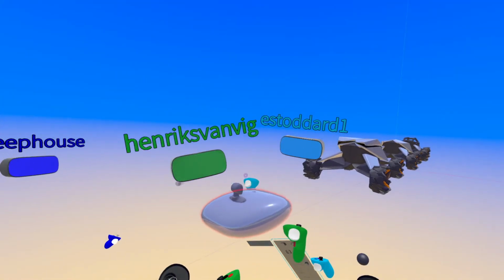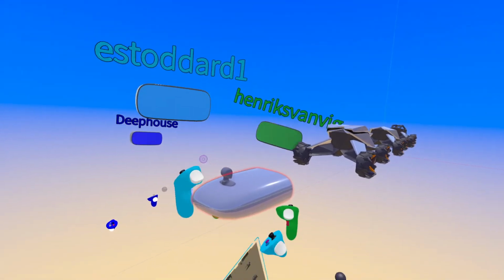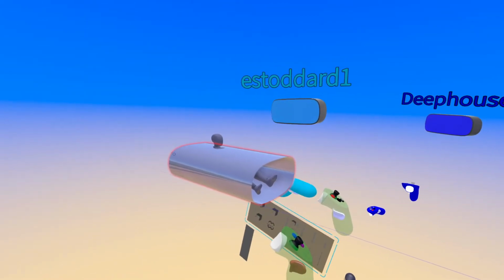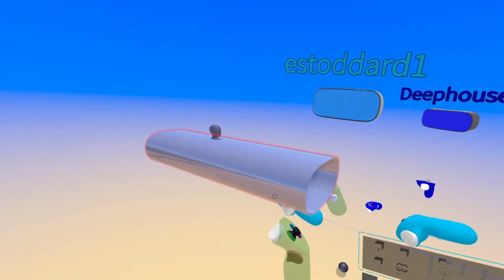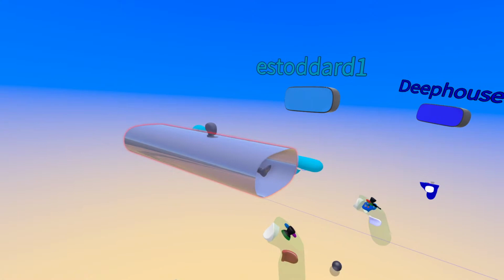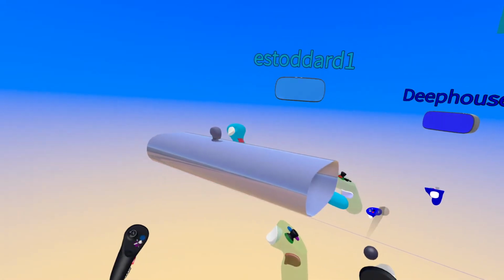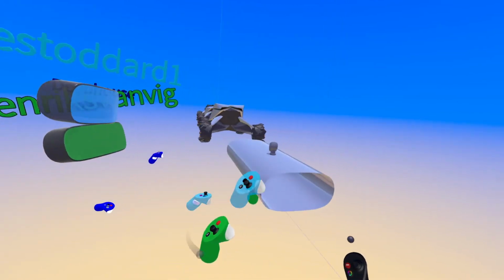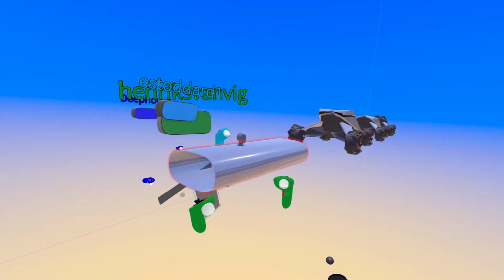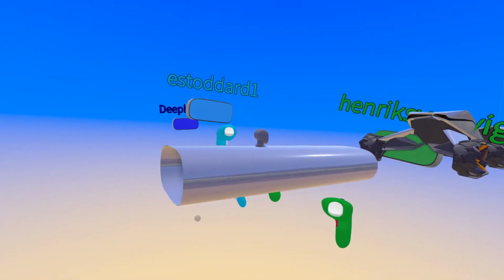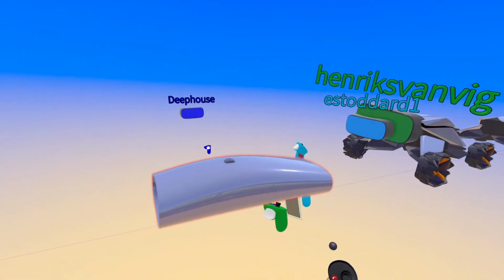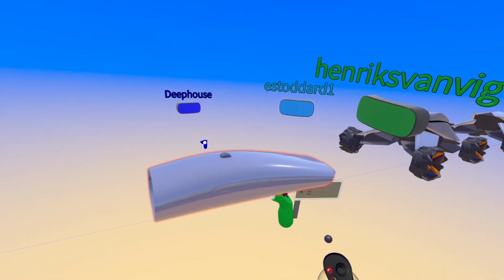starting with an egg, or maybe I go a step further and I start with a tube. And if I cut the front and back off of this thing, I have basically a tube. Now I can just stretch it out, and let's see, let's make it more of a front engine proportion. So now I can just start adding edge loops and starting to play with the silhouette of the vehicle.